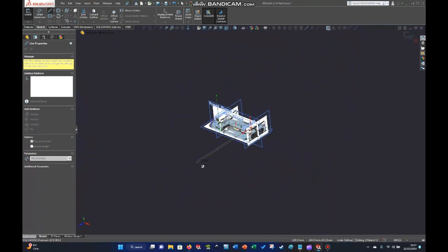What I mean by tab is that right now it turns around the Z and Y axis. If I press tab, it turns around the Z and X axis, and what I need is the Y and Z axis. So press the tab to get that. That's it, Y and Z axis. I want that construction line to come out.